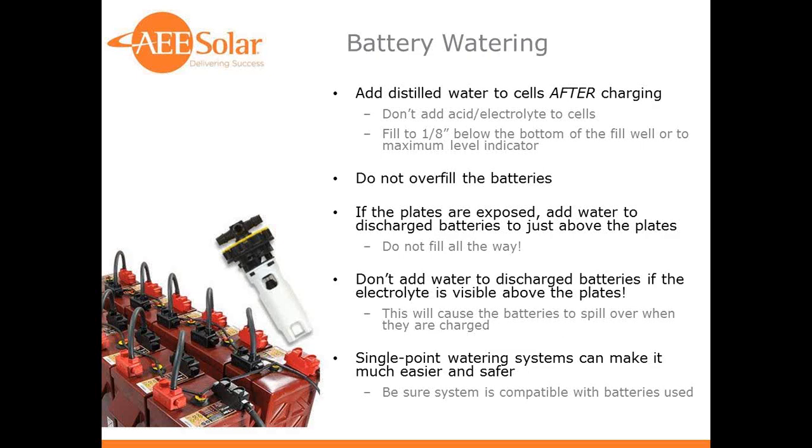As long as the plates are not exposed, you don't really need to add water until you've fully charged the battery. However, if the plates are exposed, do add some water to the discharged batteries to just above the plates, but don't fill it all the way before you charge it. You know, it is going to expand, so you don't want to have an acid spill.